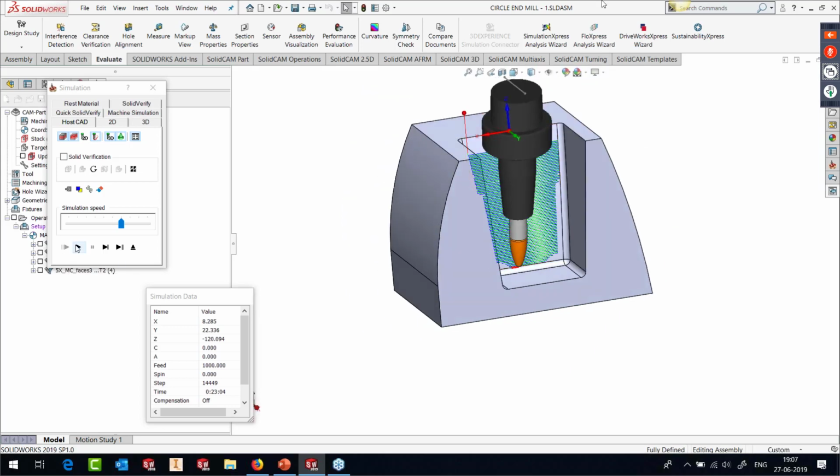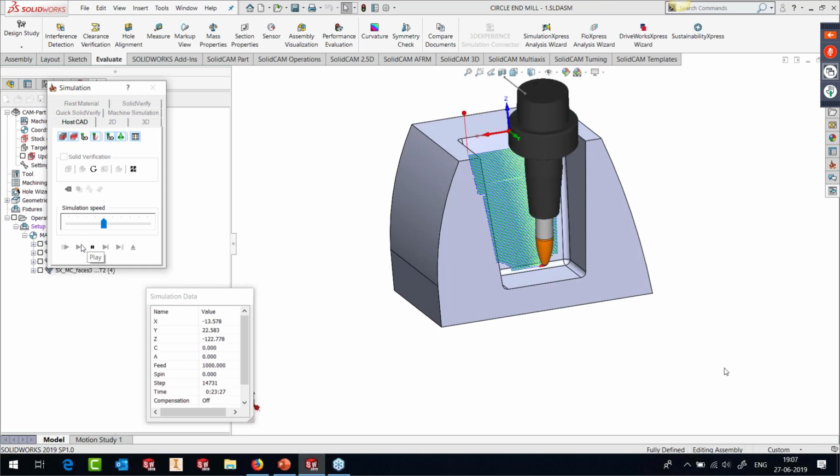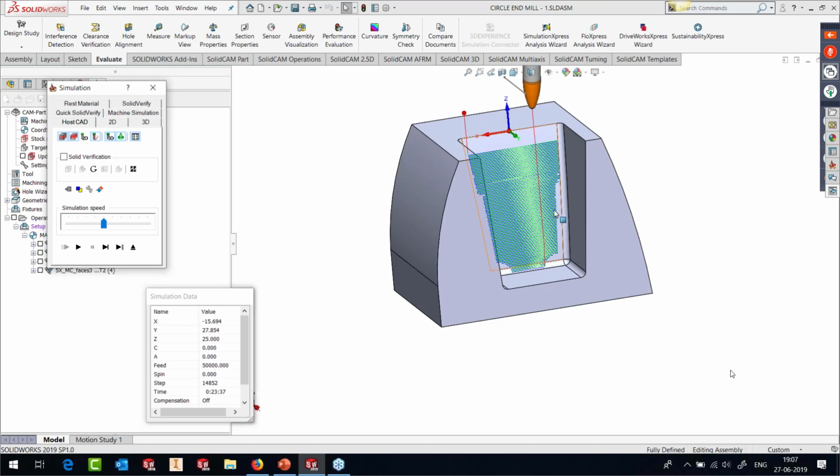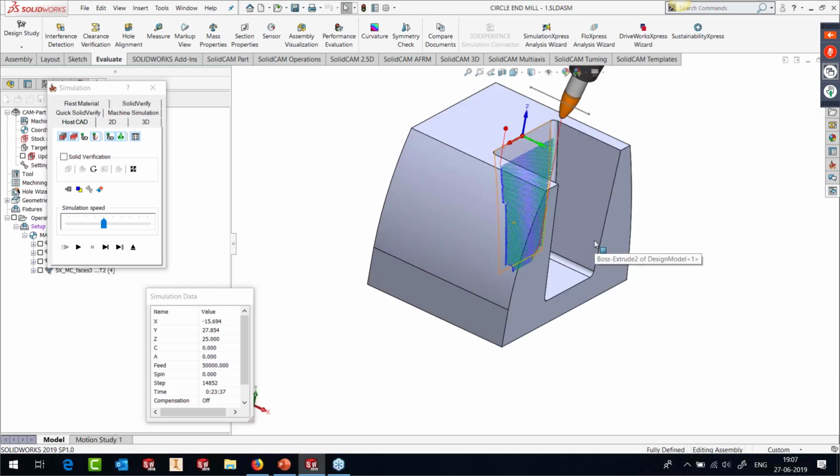What it has done very nicely is machine it till the end, and that's it. So you can use now a barrel tool with a dynamic shift contact point and machine the surface. Don't worry about the tilt angle, because the tilt angle will be calculated by the software over the surface.